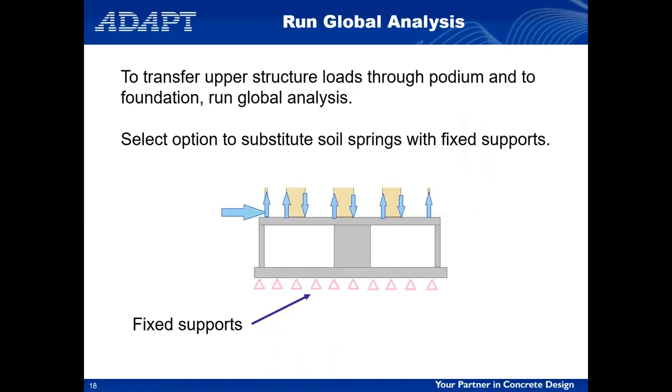So now we have our model adjusted. So now we're going to run the global analysis, and we're running the global analysis because we now want to take all of those loads, superstructure, and the loads that we just talked about defining for our concrete podium, and take those to our foundation and to our walls.